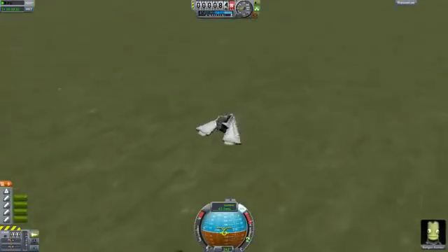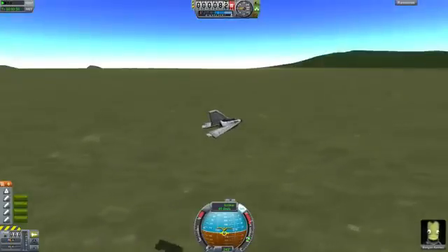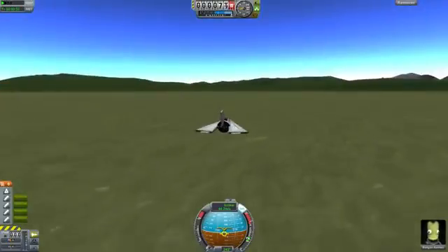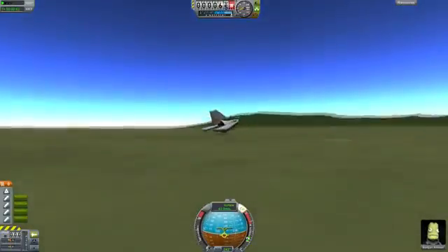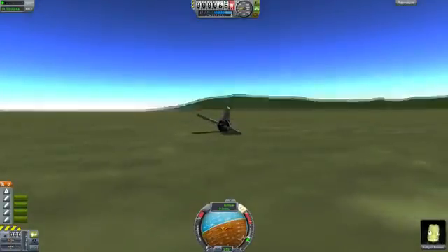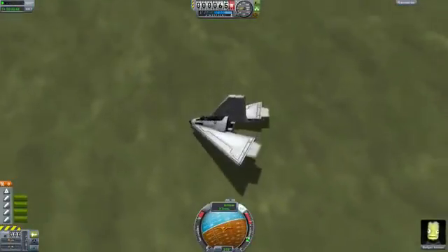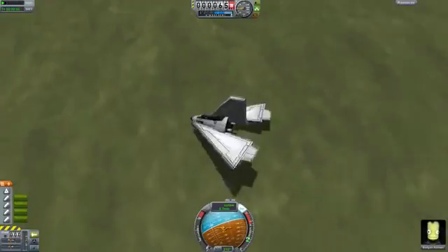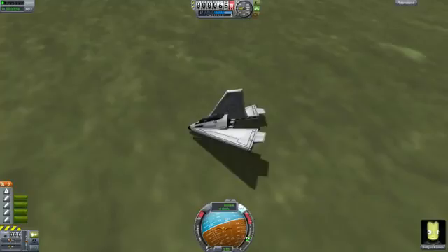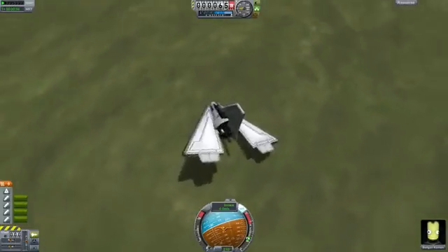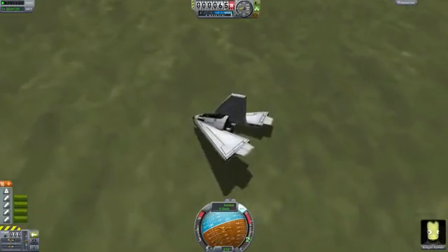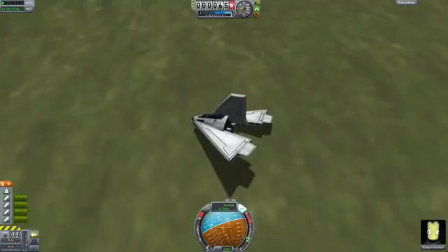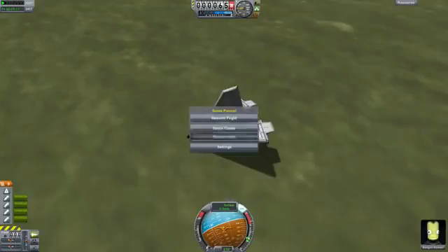And actually, you can land this thing, and of course, easiest way to land it is to use the stability control system and more or less just have it hold the nose high and slow down very slowly, bleeding your velocity up, and yeah, there you go, perfect landing. So that is entirely aerodynamics that's working there. So we need a vertical stabilizer. You can put a control surface on that if you want. You need definitely vertical control surfaces and wings, and everything needs to be behind the center of mass. So that's the basics for building an aircraft which is controllable.